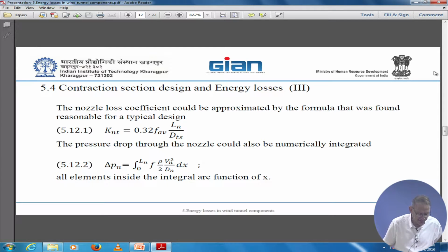First we look at the loss and definitions. You have the wire diameter and the width, which is measured between one side of the wire to the same side of the next wire. With that you can calculate again the solidity and the porosity, which are complementing each other to 1, because this is the percentage of porosity and solidity of the mesh.